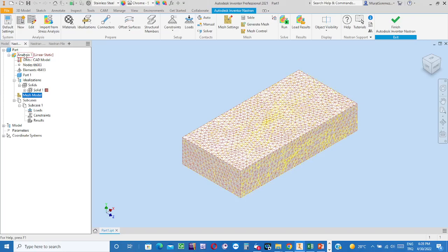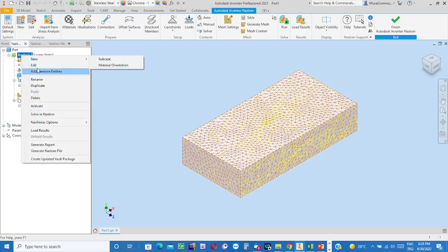And whenever NASTRAN is selected in environments along the environments ribbon, then NASTRAN automatically selects a linear static analysis option. But here it is not static analysis, but thermal analysis in this example. So bring the cursor onto analysis icon, right click the mouse and select edit option.